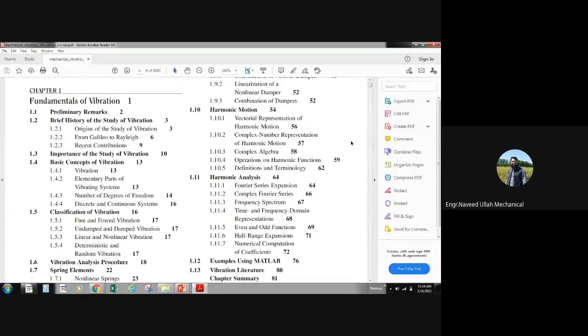There could be other types of dampers also, like the hysteretic damper, and similarly, air resistance is also a type of damping. And we also have Coulomb damping, or dry friction: if there is some vibration, then per cycle the mass is exposed to some surface and has friction. So per cycle, an opposite force is applied on the system, which tries to decrease the displacement from the equilibrium position. So that is also dry friction or Coulomb damping. It is also a type of damping. We will discuss these things maybe at some point, but you need to look at these things in chapter 1.